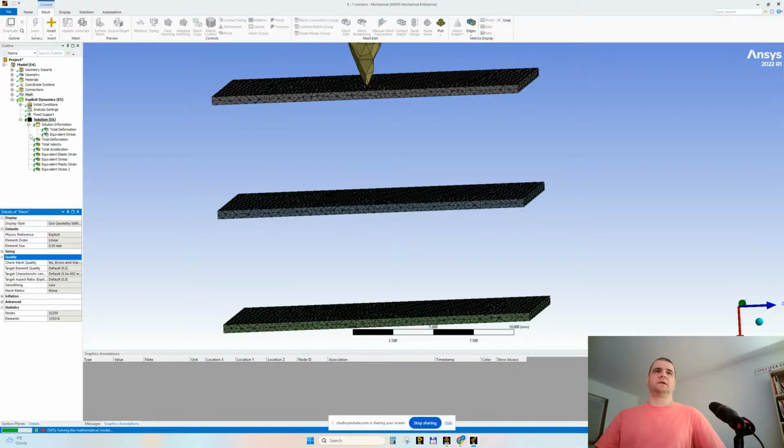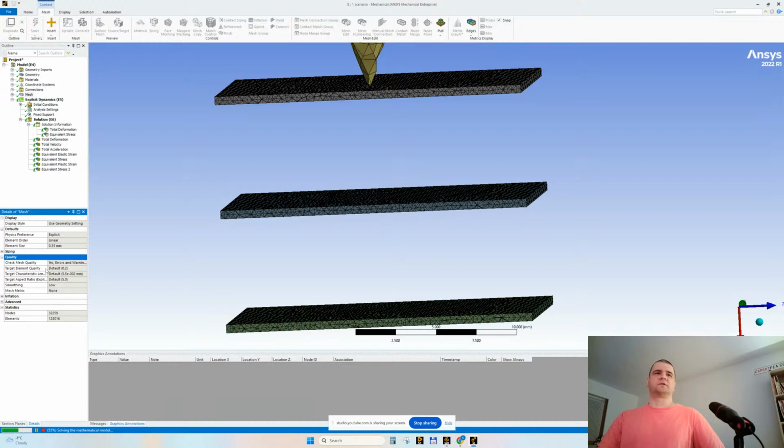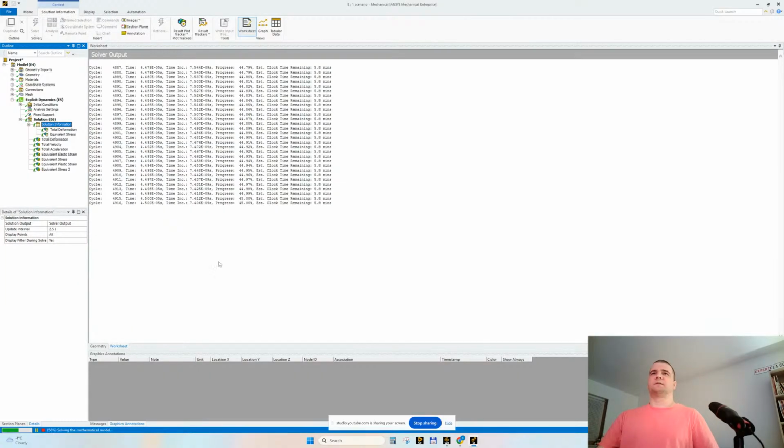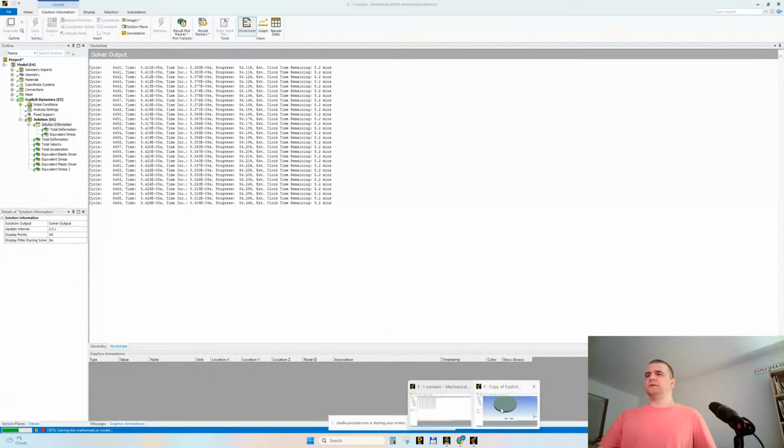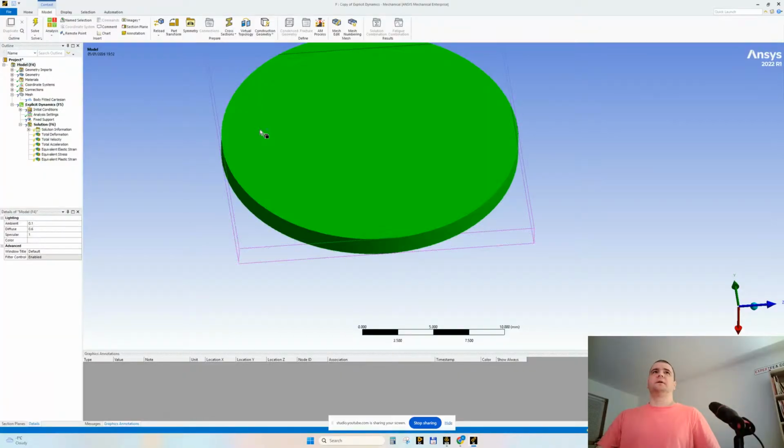In your laboratory, in your company, they should tell you what quality you should have regarding skewness, Jacobian ratio, aspect ratio, and there should be some standards in place. But here we're just learning.